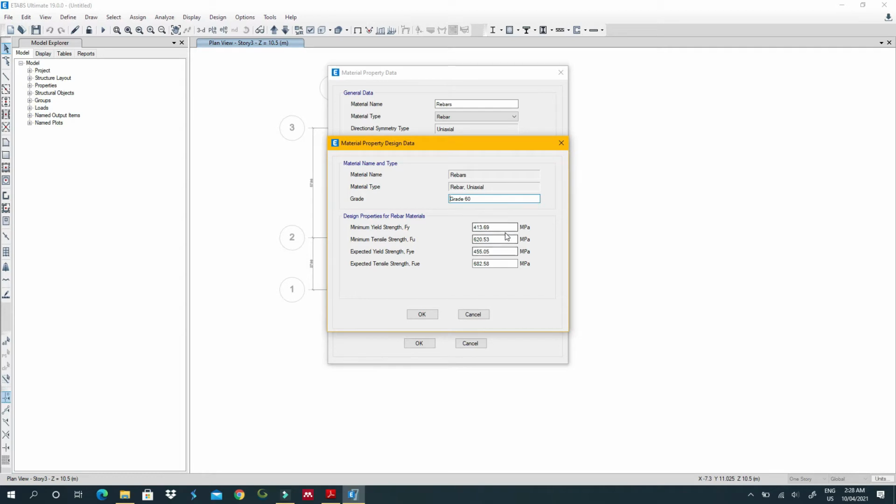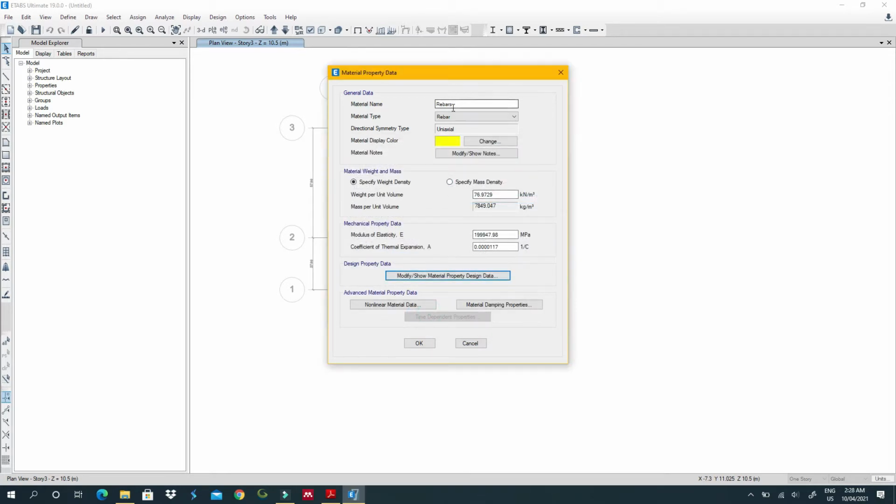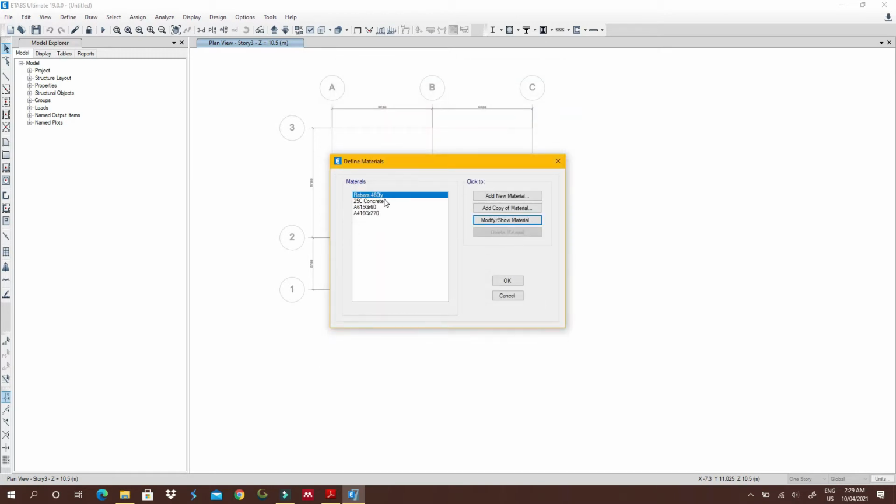So if I was doing this in real, I would just design this with this 4.413, but in my details I'd say it was 460. So I want them to use stronger reinforcement than the one I designed with. That way I will be more safe. Okay, so I'll just use the rebar and then I'll say 460 FY.